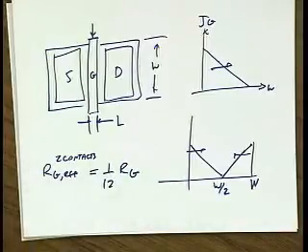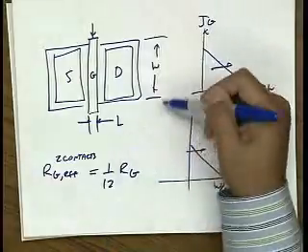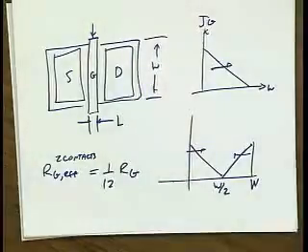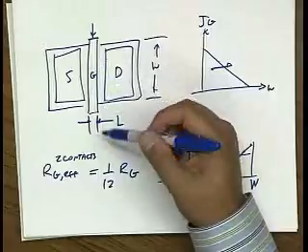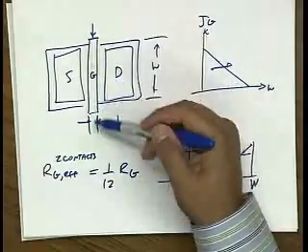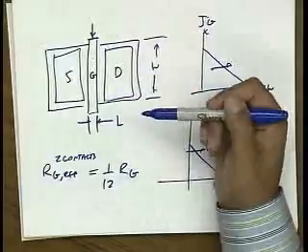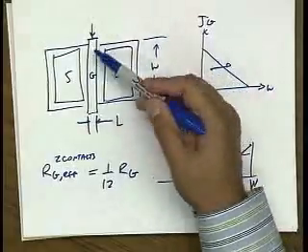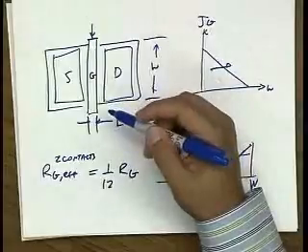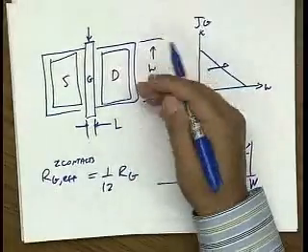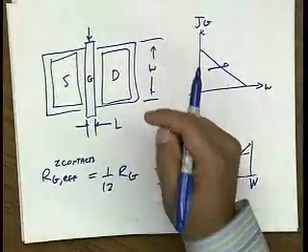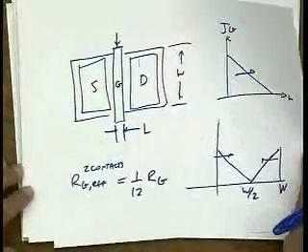So if you want to reduce the gate resistance of a FET, you can see immediately that you can do two things. You can make the fingers more narrow and put fingers in parallel to build up your transistor, and you can apply double contact to try to reduce the amount of resistance seen through here. And third, if you had a process that had a metal gate, for instance, or if you could put metal on top of this gate, then you would really be doing well because a metal has a lot less resistance than polysilicon material. And in fact, GaAs transistors, gallium arsenide transistors, do have metal gates. So they have much lower noise due to the intrinsic gate material. All right, any questions?